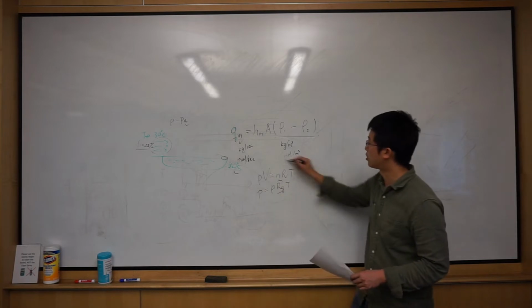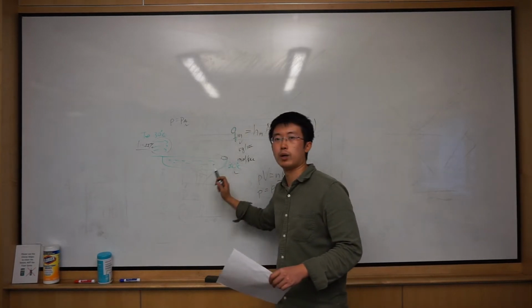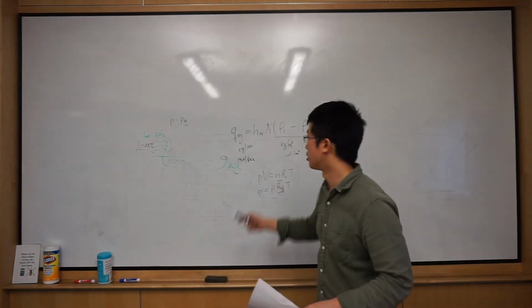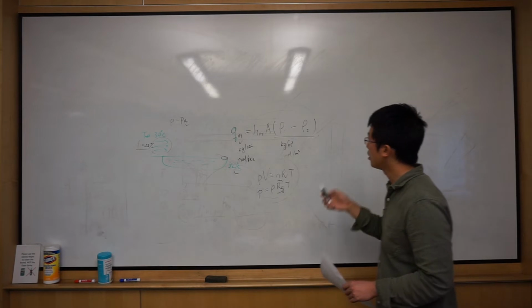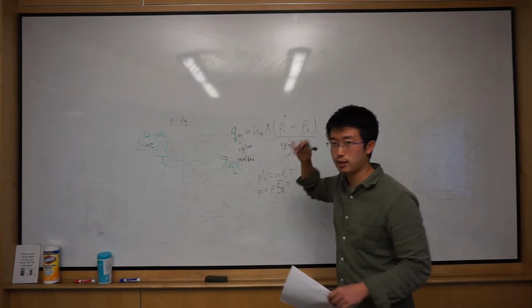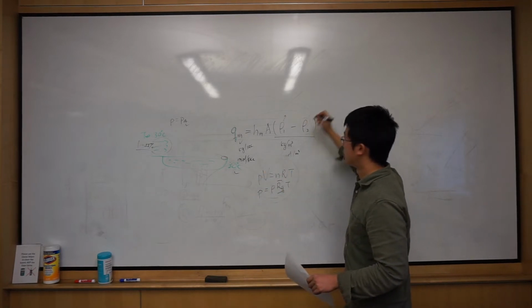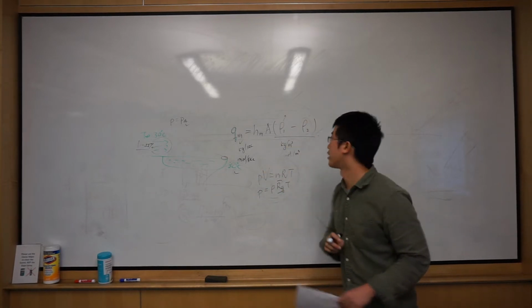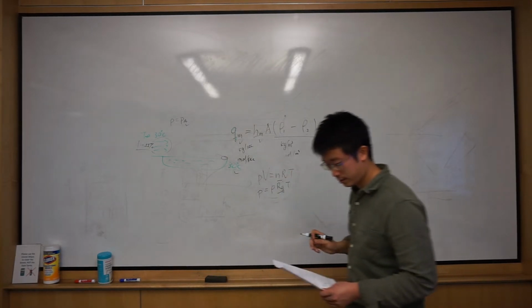All comes from this equation, because the water vapor is only a small percentage. It's not liquid, so we can think of it as an ideal gas. Okay, then we know, okay, at the surface, we use the saturation water vapor density. And this one is just 55% of that. And now we can evaluate this one.